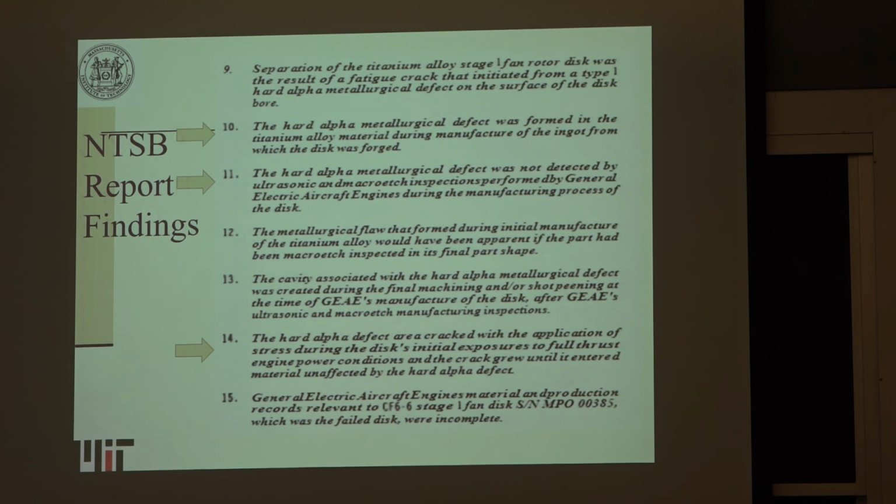The hard alpha defect cracked with the application of stress during the first initial exposure to thrust. So the first takeoff is when the crack initiated.